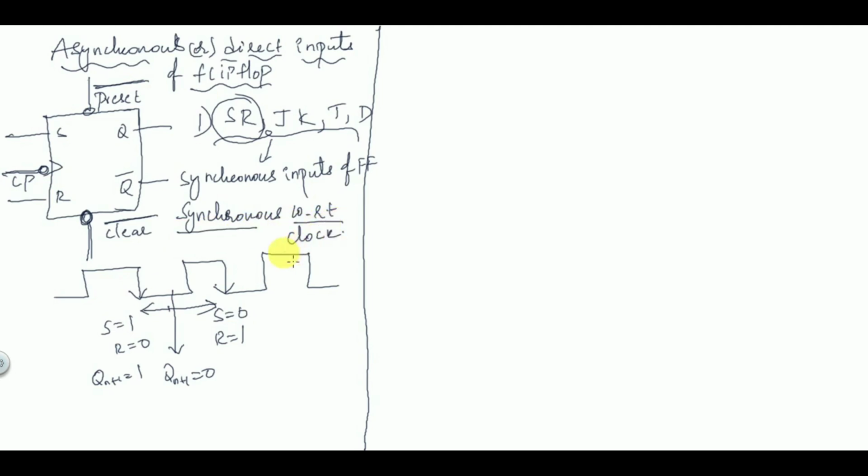That is what synchronous with respect to clock means. According to the clock pulse, that is, according to the negative edges only if it is a negative edge triggered flip-flop, you are going to change the input so that you get the corresponding change in the output. This is what happens in synchronous inputs.